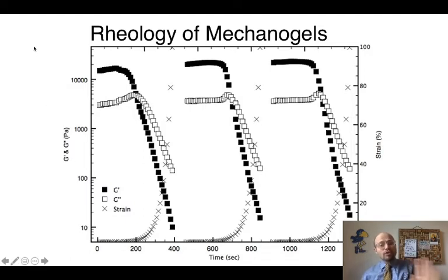And so I won't go too much into the rheology, but I did want to show a little bit of data. In this case, we have both the G' and G" moduluses, which is going to represent the elastic and the viscous. So sort of like the solid-like and liquid-like. And so we're going to take a ratio of these two. The black line in this case represents the elastic modulus and whether it is solid-like. The white squares are going to represent the liquid-like or viscous modulus.